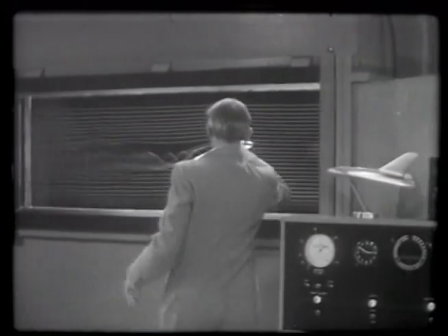You see very clearly these curls, these spirals, beginning here while the flow goes from the lower surface to the upper surface. Here underneath we have pressure. Above we have suction. And the air flows from the pressure side to the suction side.